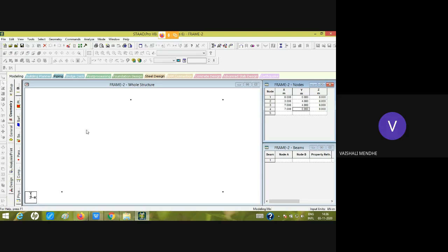Okay, and then click on the empty space, and from the top of the side you can see the various views. There is a front view, side view, top view, bottom view, and isometric view also. From these, we always have to select this view, where you can see my cursor. So this is a front view, and it is already selected here.